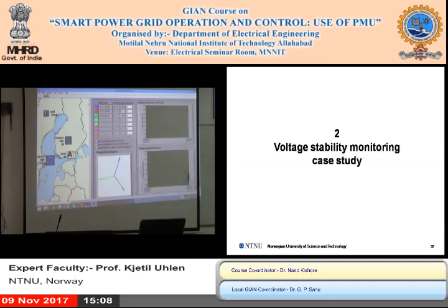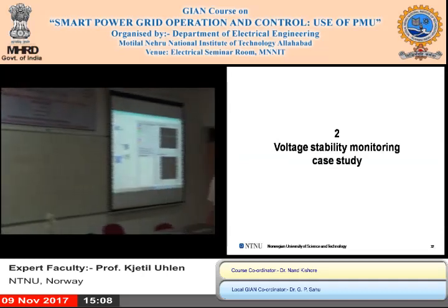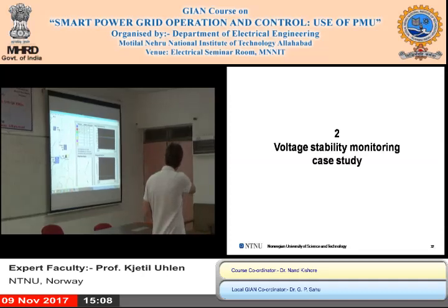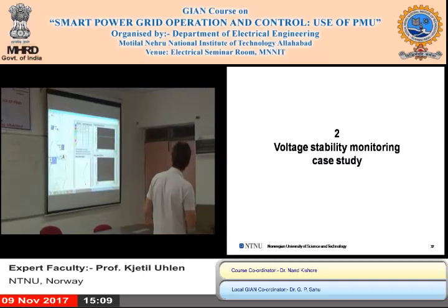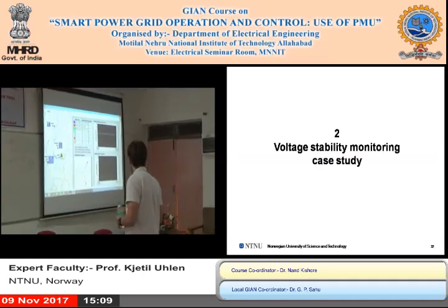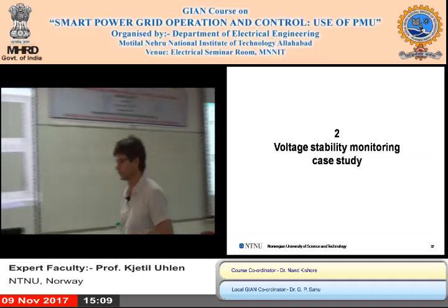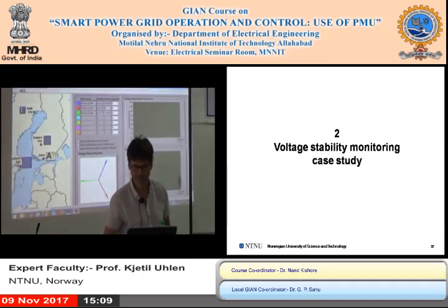So at any deviation from 50 hertz, these phasors will move. As I said yesterday, if the frequency is 49.1 hertz, it would take 10 seconds for them to go one round, one circle. Now it looks like the frequency is quite good and quite stable.